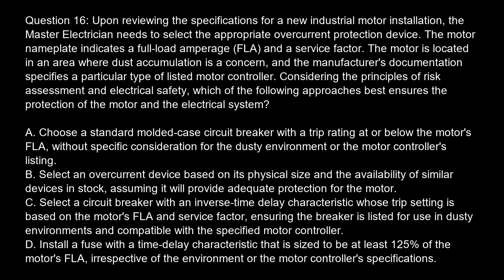Option C. Select a circuit breaker with an inverse time delay characteristic, whose trip setting is based on the motor's FLA and service factor, ensuring the breaker is listed for use in dusty environments and compatible with the specified motor controller. Option D. Install a fuse with a time delay characteristic that is sized to be at least 125% of the motor's FLA, irrespective of the environment or the motor controller's specifications.